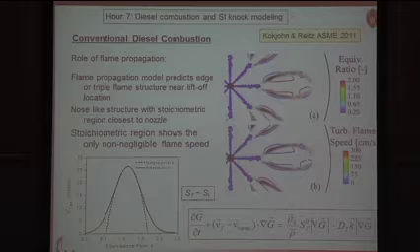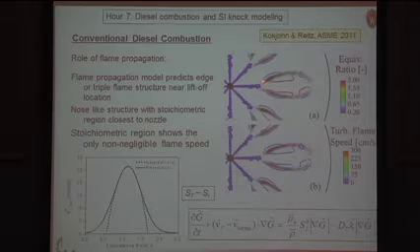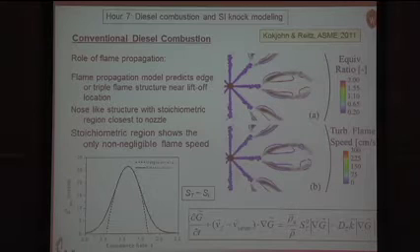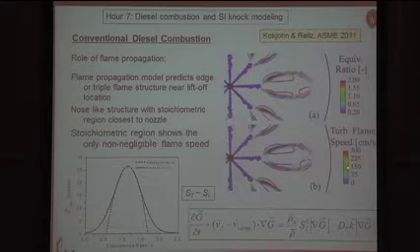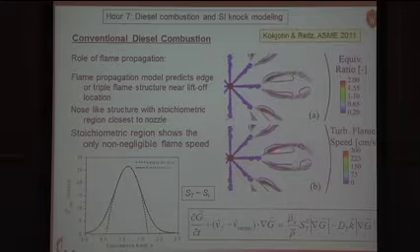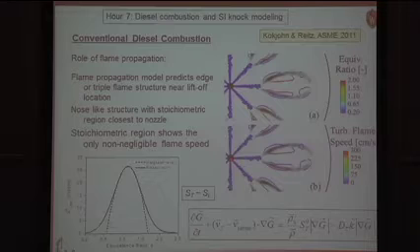And so, again, we have very low flame speeds over there. In fact, the only place where the flame speed is likely not to be small is right here at the tip where the equivalence ratio is around 1. And in fact, if we plot the turbulent flame speed along the flame surface here, we see that it's basically on the order of 100 meters per second or so right here at the liftoff location where the OH starts to be in evidence. So basically, this lifted flame, here's our liquid, here's where the flame is located.